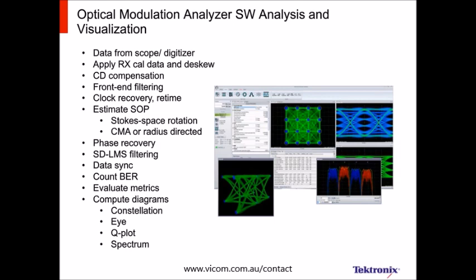So you might need to turn on adaptive filters. As soon as you turn on adaptive filters, you're complicating things a little bit, because this is a real-time filter that's being designed by an algorithm to compensate for all frequency domain impairments that are present. That will include polarization mode dispersion, but it will also include, say, cable loss in the transmitter. So it's basically fixing everything. When you turn on these adaptive filters, the constant modulus algorithm is one of them. The symbol-directed or decision-directed least mean square is another example. When you turn these on, it's going to be more difficult to get agreement between the suppliers. I guess what you're doing at this point is perhaps trying to say just how good could the system be if we turn on all these adaptive algorithms.